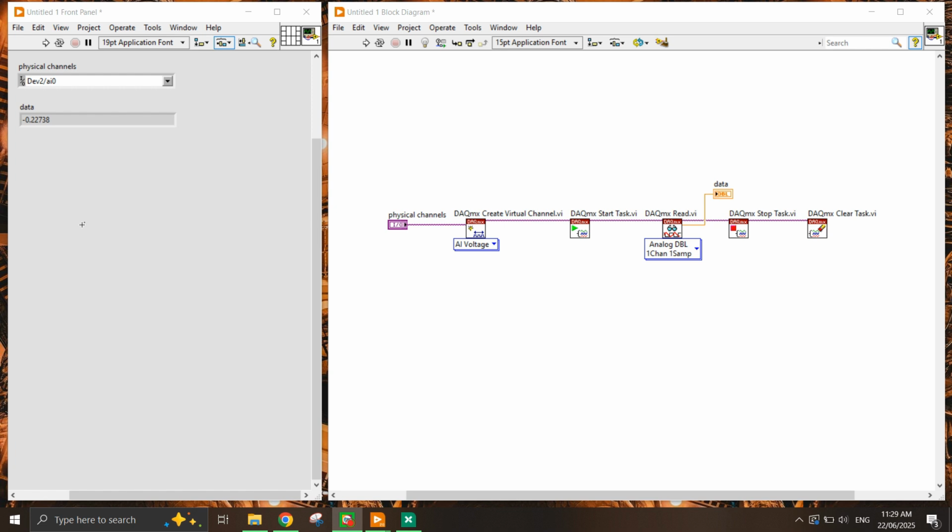So today we will look into how to use Python code with the DAQmx driver and how we can use that with simulated and also actual hardware connection. Here I have a simple basic analog acquisition code using the DAQmx driver, where we will be measuring the analog input voltage value.